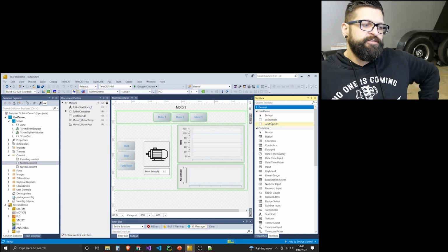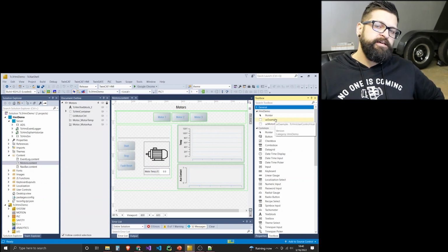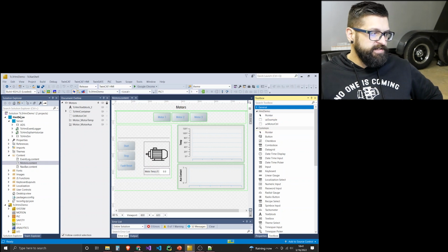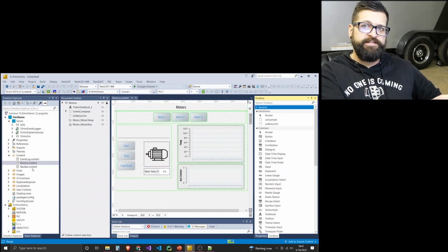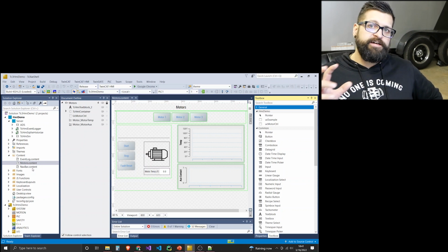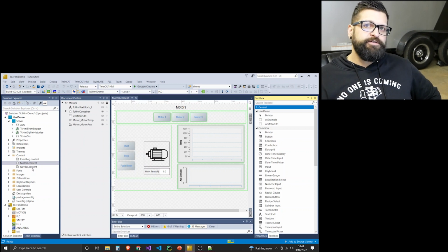And so those are the first ones that are displayed, and it's under the heading of HMI demo because those are user controls that I've created in this HMI demo project. As you can see over here, the name of the HMI project is HMI demo. The other great thing that I'll bring up is because all of these are files, if you create a new project and you don't have a template project, if you just finished one job as an integrator, you've got another job and you want to bring over a lot of that code base that you've already worked on, because these are just files, it's really easy just to open up your new HMI project and copy and paste these user controls or these content pages or whatever they are over to your new project.